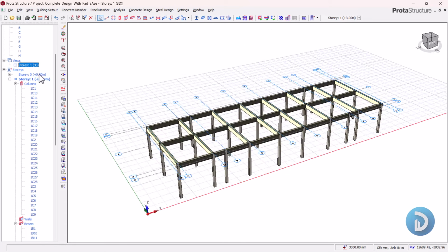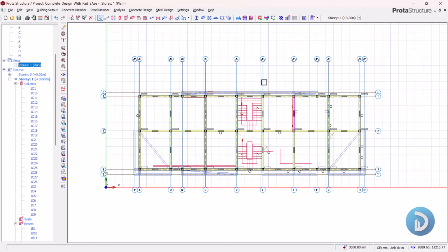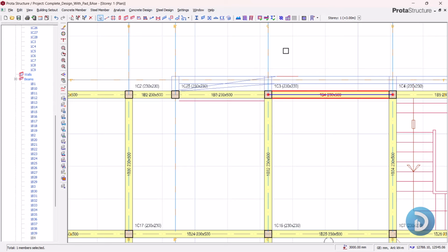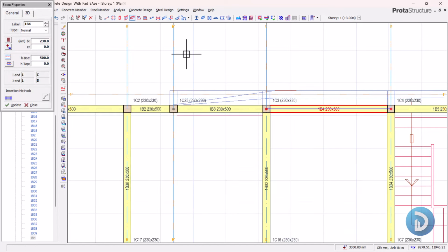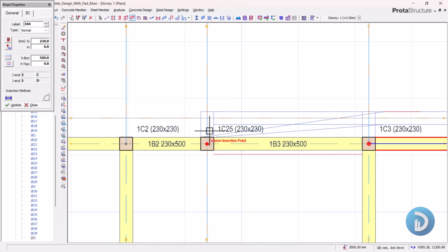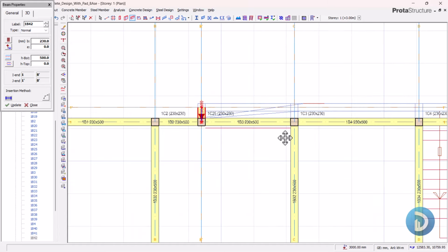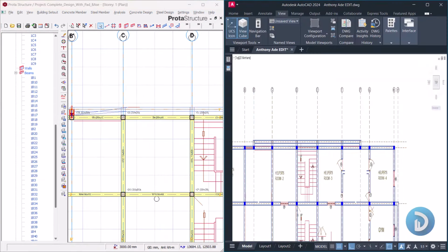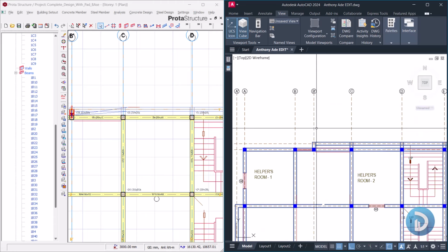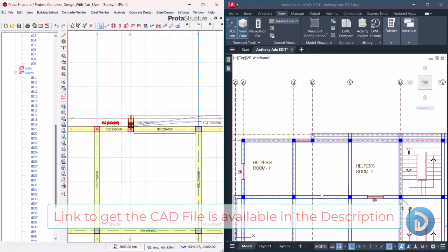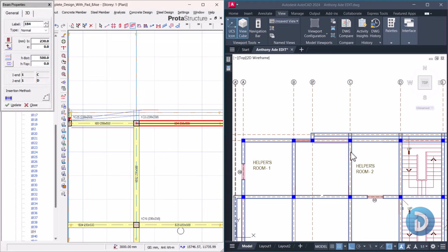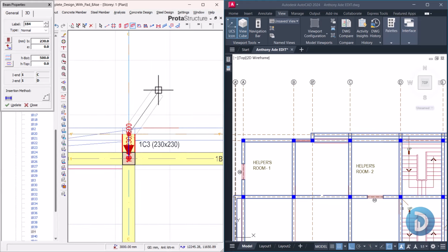So now we have to create our cantilevers that will in turn receive those proposed new columns. Okay, so we'll click on beam, right click, take these properties, and we'll say from this part we'll have a beam that will cantilever from here to here. Then let's put this side by side with the AutoCAD file. Okay, so on grid line B asterisk, which is this, we've already created our beam. We'll click, come to properties, then another beam runs on grid line C to support the newly introduced column. So we'll click from here to here.